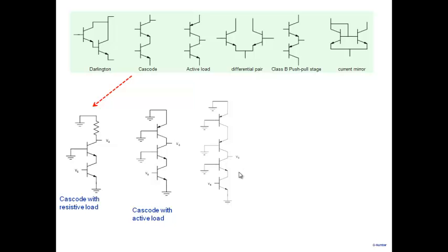So what are the alternatives? As I said, one can take these elements and play around with it. So another one that you can think of, we call it cascode with cascode load. This is a cascode and the load is also a cascode. So here's another amplifier. And we have the tools with us right now that we can take this, we can predict what the gain is, what the frequency response is, what the input resistance is. We can predict each one of them. We can easily calculate what the gain of this particular stage is going to be, using the method that we talked about: break it up and reuse the results, 4 or 5 results that we had said. Based on that, you can calculate the net gain at this particular point here.